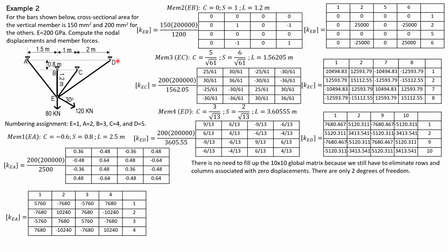see the reaction forces. So 1 and 2, the forces are F1 equals 120 cosine of 30 positive, so 120,000 cosine 30. F2 are both downward, so we have negative 80,000, and the component of 120, which is negative 120,000 sine 30.